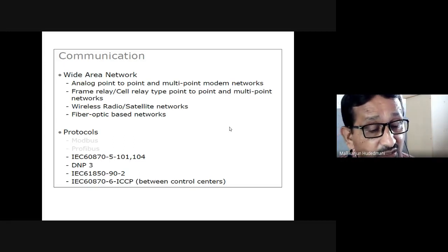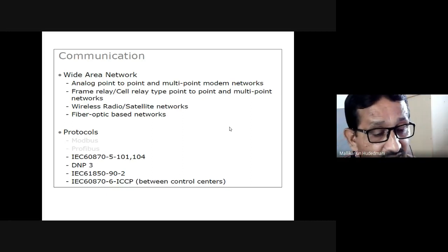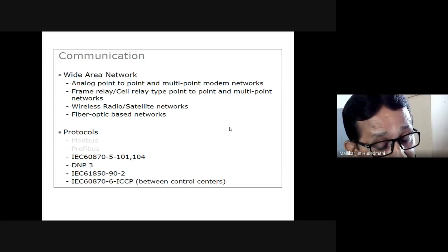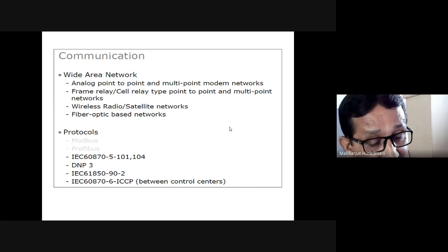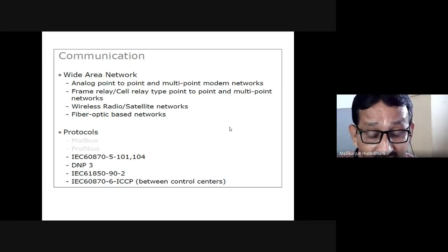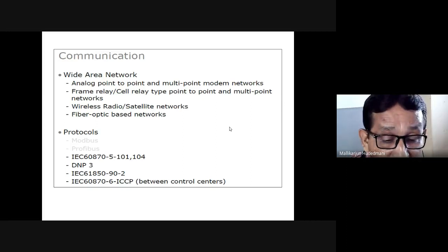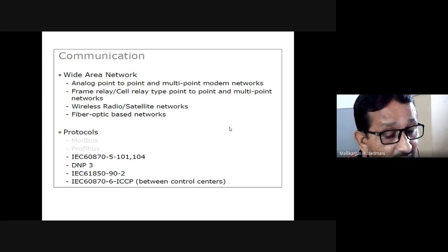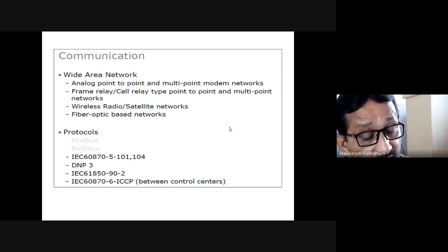Then comes standardization among the components. Manufacturer A of American, manufacturer B of German, manufacturer C of Japanese or anything of European origin, those corporations set up their own monopoly. They developed the algorithm and the language with which they get connected and respond, like Modbus, Profibus and different ones. Later, when you want to connect an intelligent component available in the public market, when you purchase it, it must be capable of communicating with peer devices from other manufacturers, so that the exchange of data between them does not become a challenge.